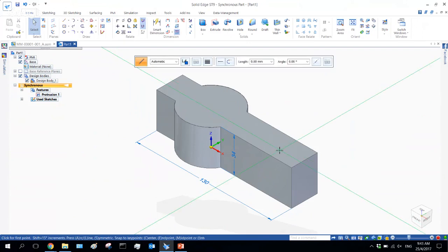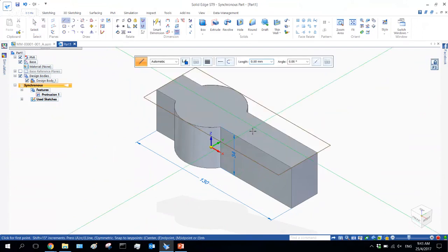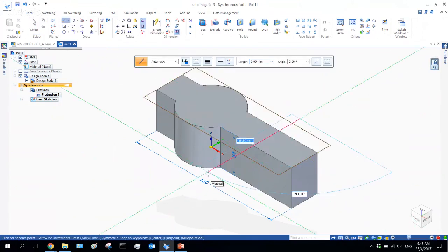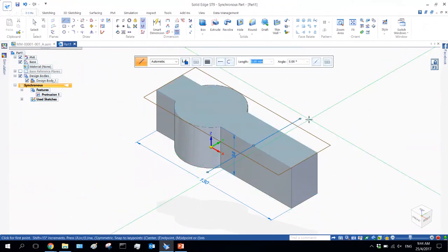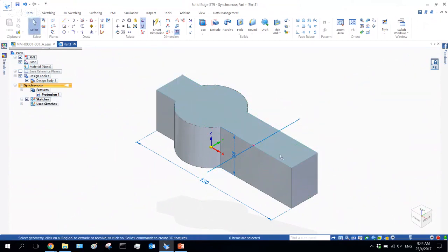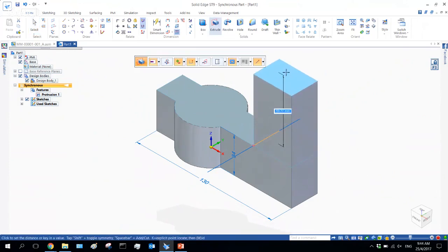And I want to make some line up there. But in Solid Edge, it's very simple. You don't need to trim the extended line over here. What is important is that you want to divide the region into two, the left region and the right region. And if you want to modify it, just click it and pull the arrow over there. Just like that.